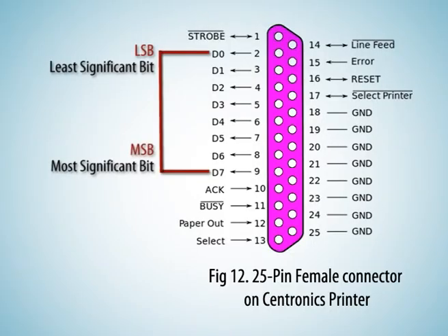1. 8-bit data bus signals D0 to D7, where D0 is LSB and D7 is MSB or most significant bit. The 8-bit word usually was an ASCII coded character. In the complete set, some characters were printable text characters, some were special or graphic characters, and some were control characters which manipulated printer's setting and print style.